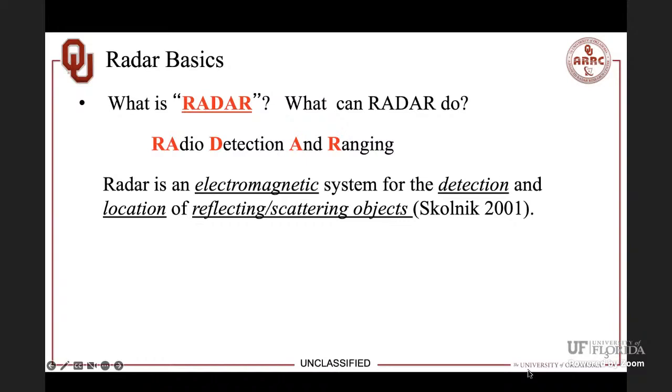So here I want to emphasize what kind of target. I use this word target because I want to present it in a more generic form. From a military point of view, they are interested in point targets, like missiles and airplanes. Those are called point targets. For weather radar, we look at weather, which we call a distributed target. That means things typically much larger in space, extended over kilometers, and larger than what the radar resolution can see. That's what we call a distributed target.